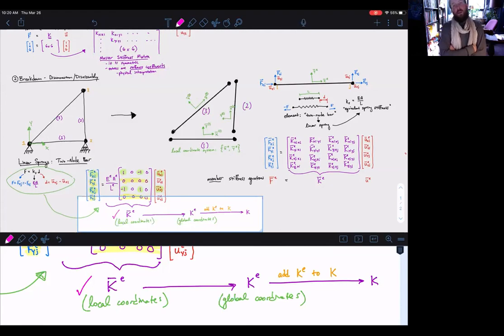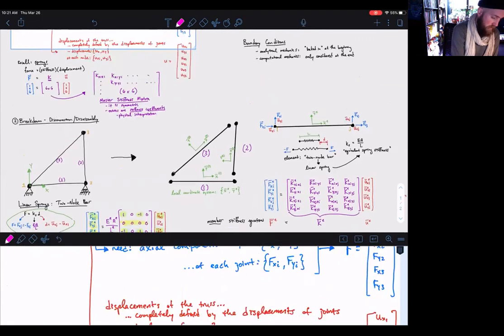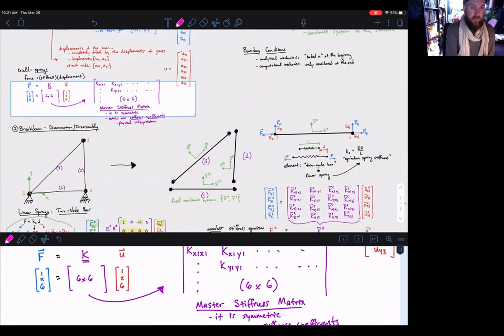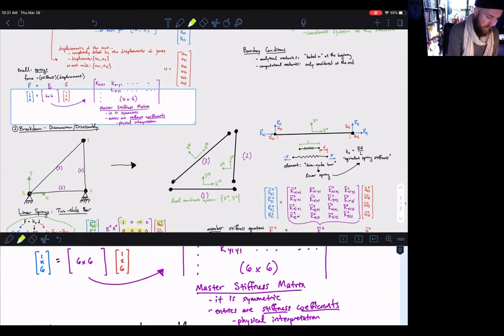Basically because we end up constructing a global stiffness matrix. And when we reassemble the structure, we want to say that there are going to be some unknown displacements. So let's pretend we're applying forces to a structure. So we know F, we're solving for U. We want to leave U be a generic set of unknowns. As you go back to this part of the equation here, we want to leave U as generic unknowns that we're going to solve for in our problem.